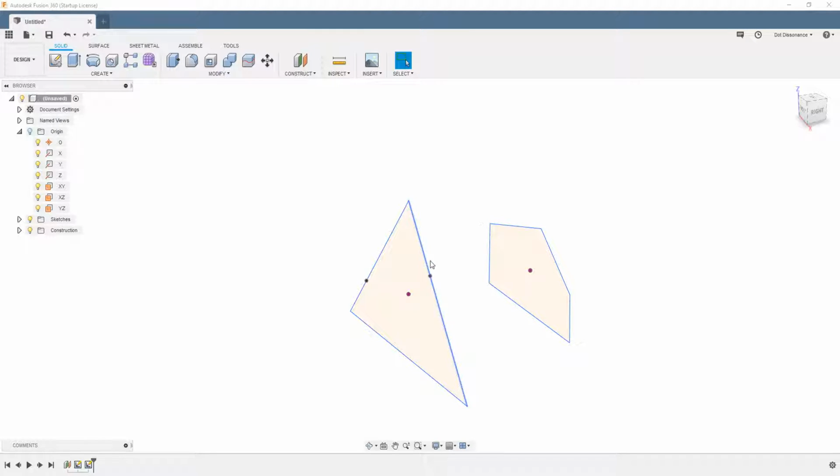But I can't do this. They don't have a three-dimensional line here in 3D space. What you have to do is go make a sketch, but this is weird and important: don't think of a sketch any longer as a sketch plane that you put a two-dimensional object on. Think of the concept of a sketch, like over here, sketch 4, sketch 5, as a container, almost like a folder, but a container for a certain function. This is super weird, but it works pretty good once you get used to it.